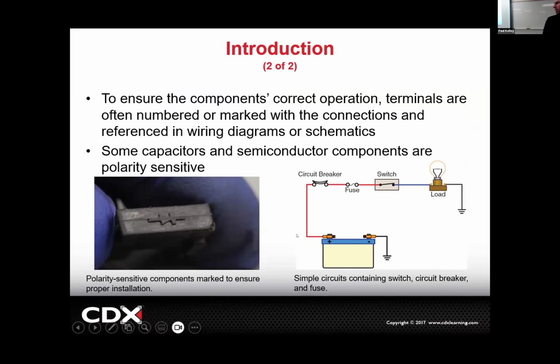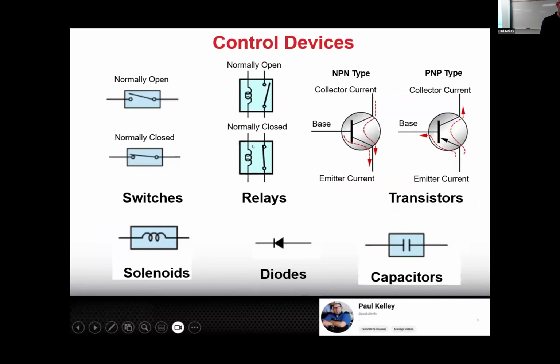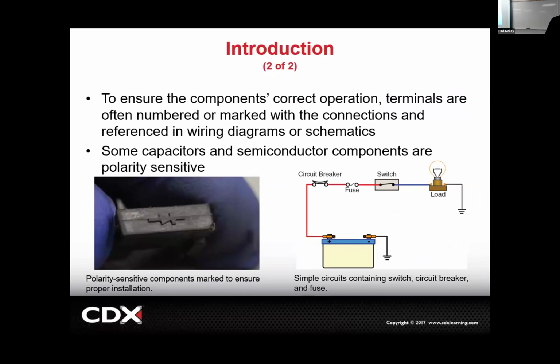You've got this thing, by the way, that's a battery. The battery symbol can vary. This, for example, is a battery symbol, but they do vary. It can look different. Obviously, the battery's connected to chassis ground. It comes out of the positive. It sends it up through, like in this case, we're showing you protection devices. It goes through a circuit breaker.